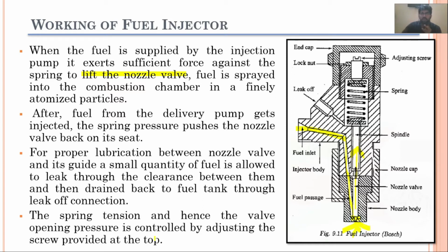After fuel from the delivery pump gets injected, when the fuel from the injection pump has cut off, this spring will apply the resisting force and bring the nozzle valve back to its original position.